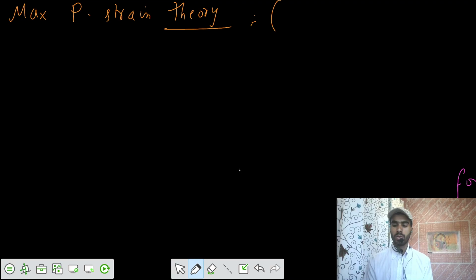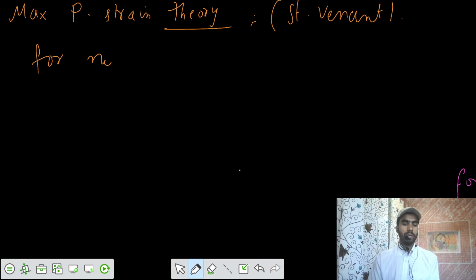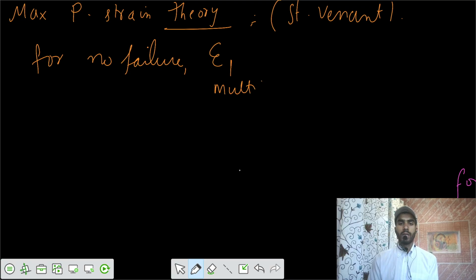That's also known as Saint-Venant theory. It says that for no failure, your major principal strain in multi-axial loading should be less than or equal to your strain in uniaxial testing, that's the yield strain in uniaxial loading.